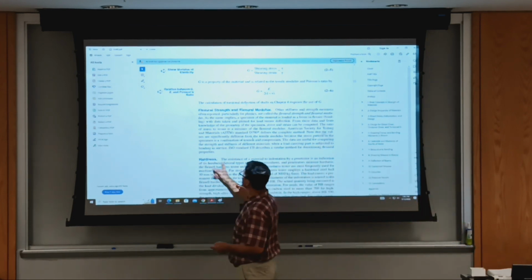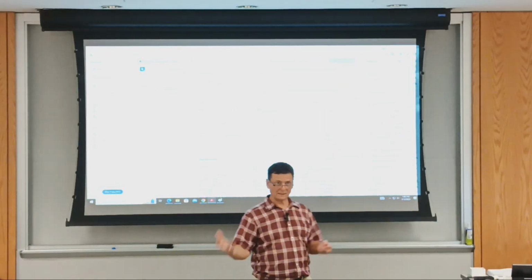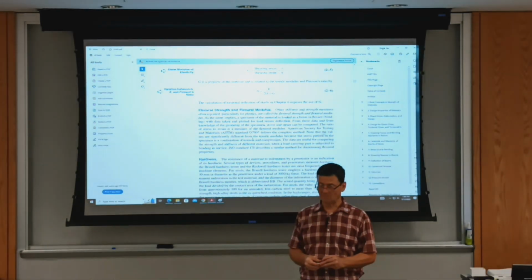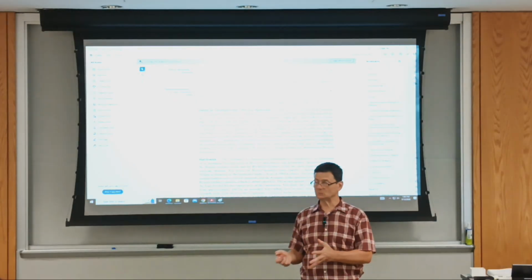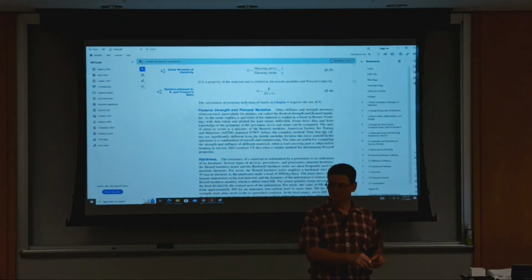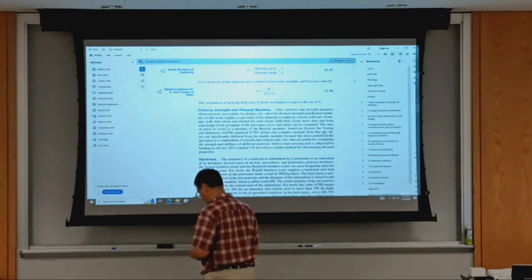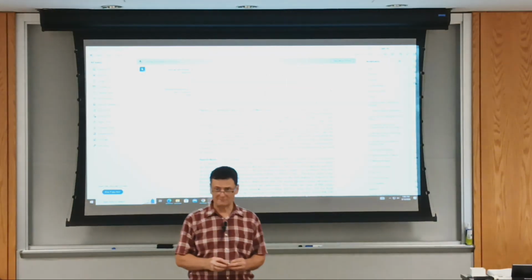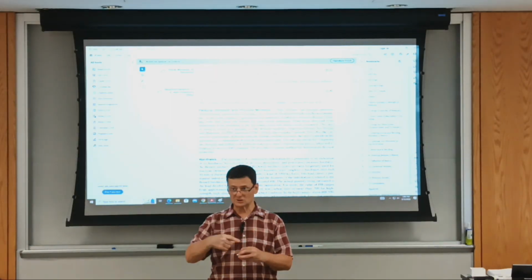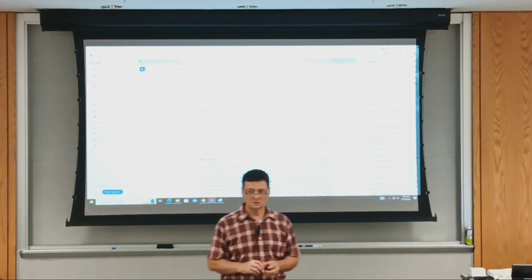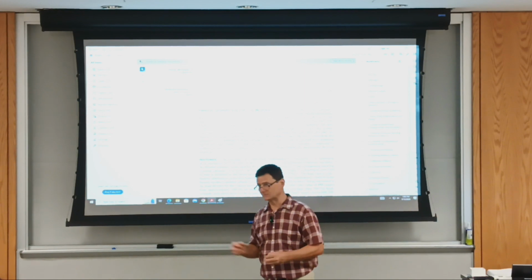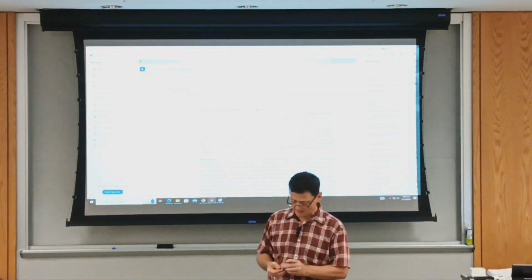So hardness is resistance to wear. Okay, and hardness and strength go hand in hand. You'd expect a hard material to be also strong, although hardness can also translate into brittleness. And for that reason, you may see parts that have heat treatment done just on the surface. It's called case hardening. They're hard on the surface, but the core is softer and ductile to provide wear resistance on the surface and toughness. We'll discuss toughness just a little bit.